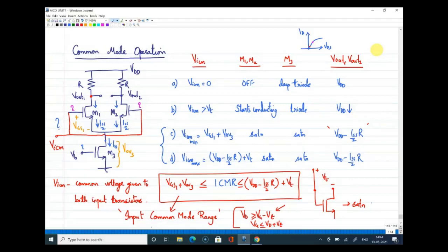The response remains the same. Now, if the response remains the same, when you measure the voltage as a differential voltage, that is, we are measuring at this point with respect to the other point, since both nodes are responding equally to the signals, the difference voltage will always be zero. That will get cancelled out. So that is the beauty of the circuit.